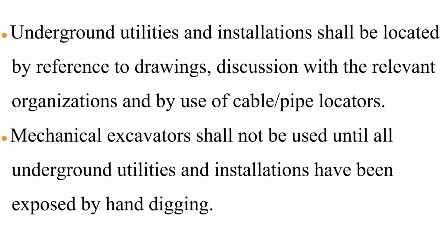Underground utilities and installations shall be located by reference to drawings, discussion with the relevant organizations, and by use of cable and pipe locators.